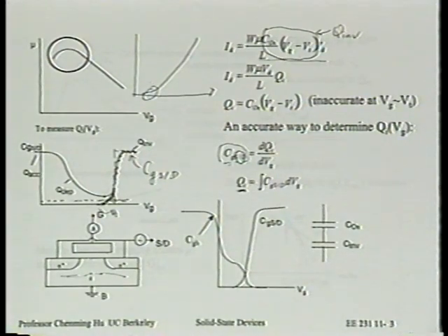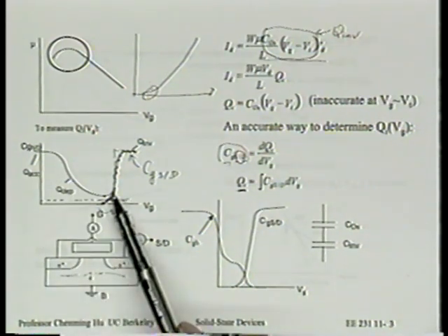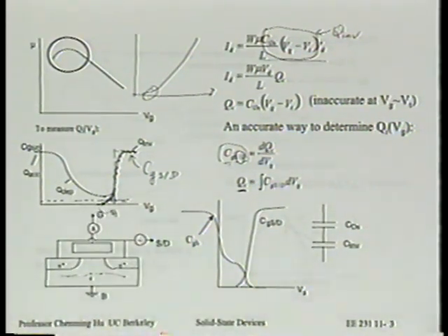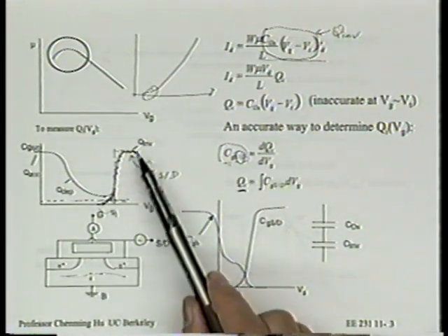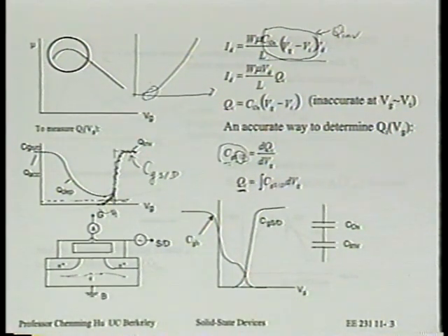Right. So this actually is a very, very good plot, this technique. It's very, very good. In fact, it's a better way to determine oxide thickness than using these, because using these, I already mentioned to you, there are problems like the probe pad capacitance, for example. And you lift the probe, maybe the probe pad capacitance goes away, but what about the probe capacitance itself? So with this, you don't have to do anything. You just keep the probe down, but you still have a reference to know where it's 0. Following what I'm saying? All right.